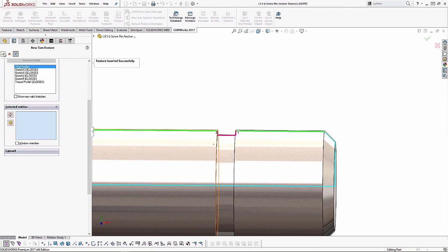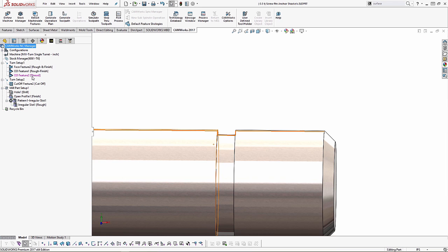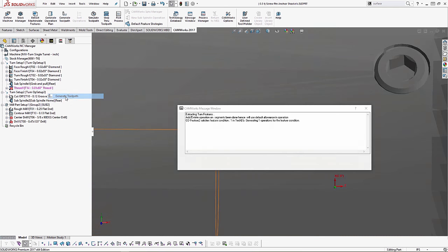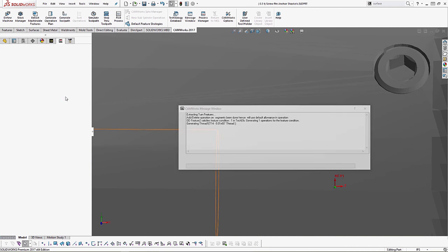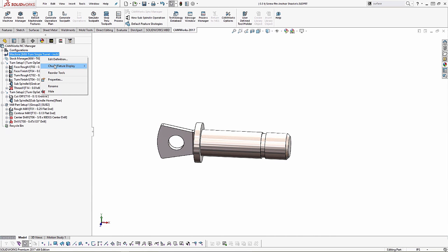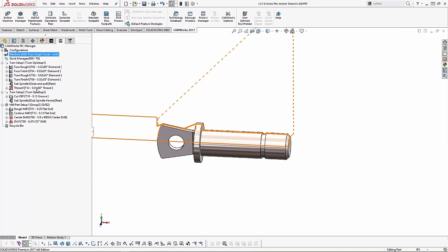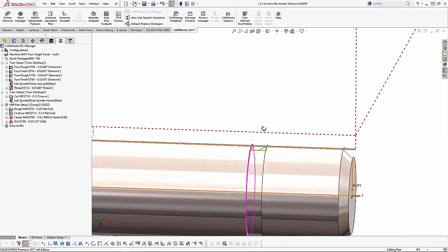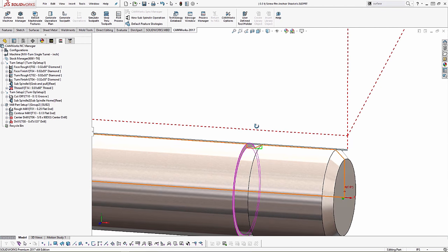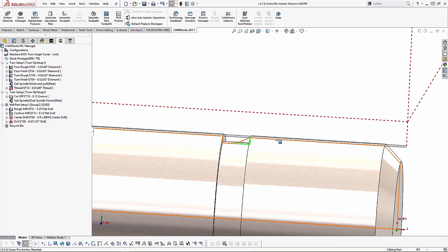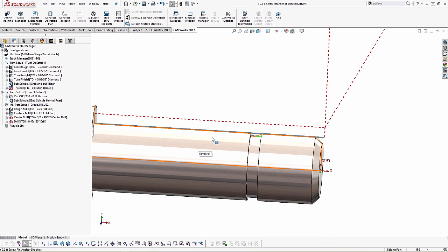then it would scream at me. It would give me an error. But now it actually lets me create it. And generate toolpath for it. And it goes across the gap here. Okay, so that was not possible before. The only thing we could do before is we'd have to create a feature for the first segment and a feature for the second segment, and we would not be cutting them at the same time like we are here.